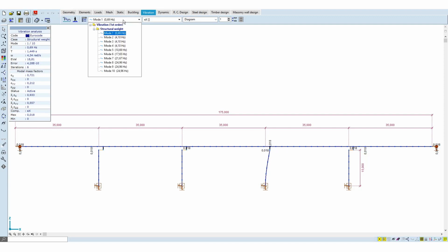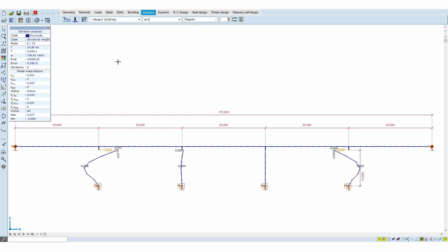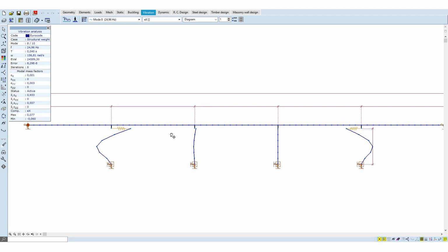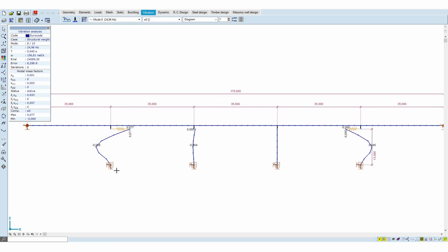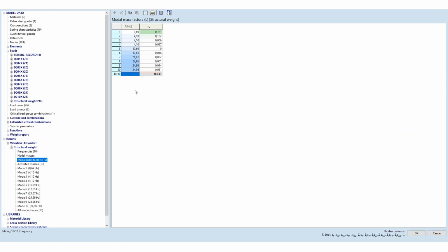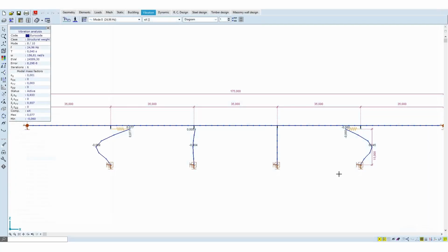The other mode shapes are the different vibration modes of the other three piers, but they have no influence on the global longitudinal seismic behavior. They could be simply modeled as independent cantilevers. The dominant vibration modes can be found in the tabulated results. We have two dominant frequencies to consider later on: 0.7 Hz and 4.1 Hz, associated with the pier deck system and the freestanding piers respectively.